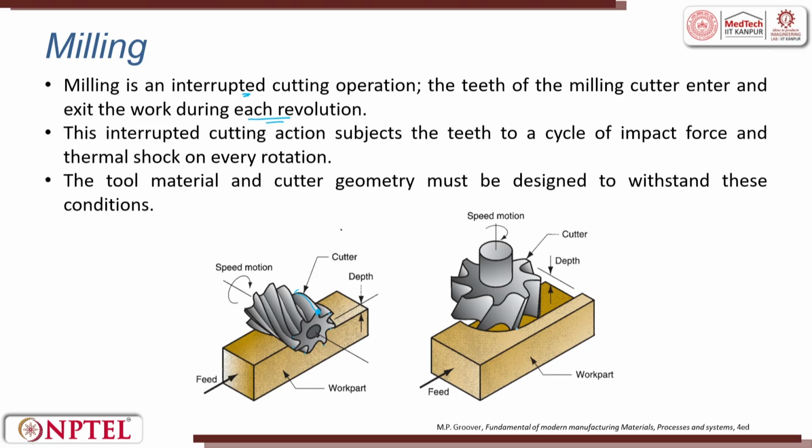So, what they are trying to say is it enters as you keep moving. If you see here, it enters for cutting. So, there is a chip which is removed. After the material is removed, the tooth exits. The interrupted cutting action subjects the teeth to a cyclic impact force and a thermal shock on every rotation.